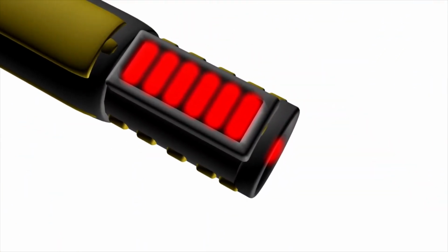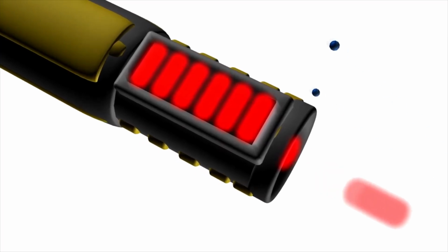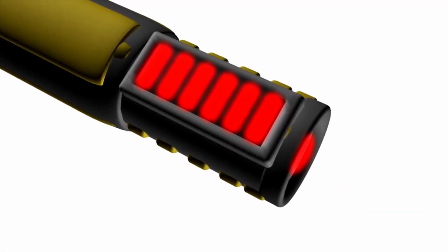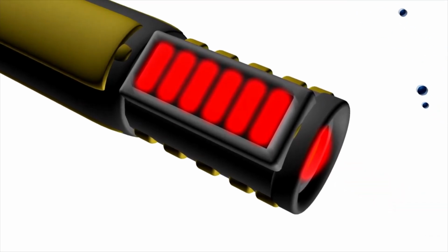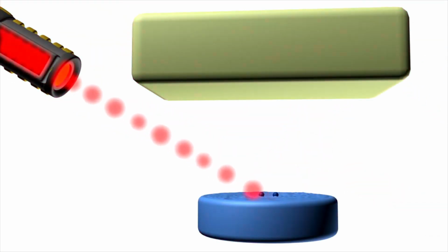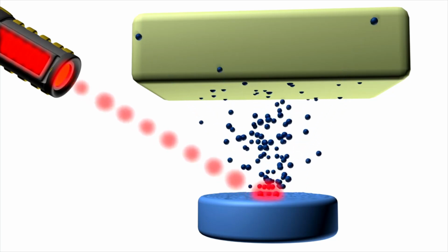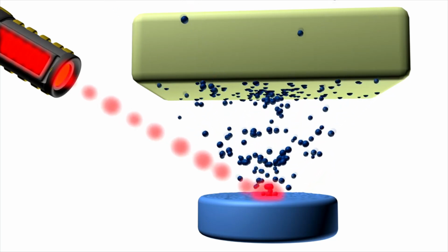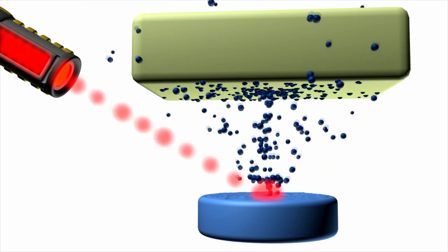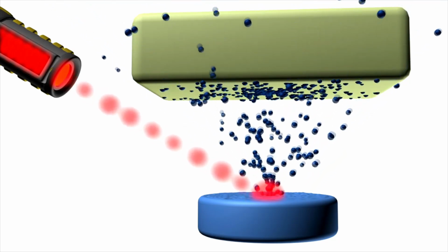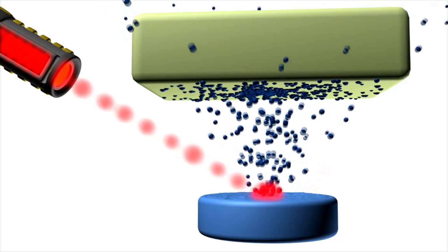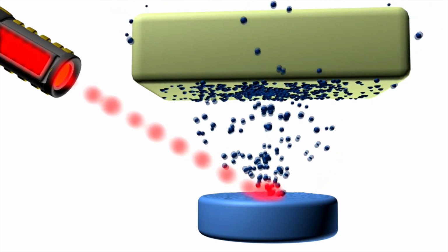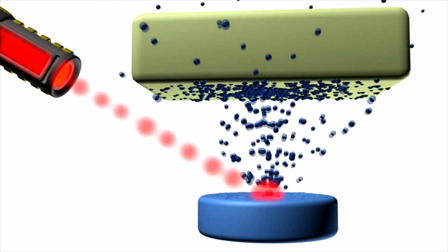The intensity, wavelength and length of the laser pulses also have a significant effect on the excitation mechanism that takes place on the target surface. For instance, using a laser with short pulses, shorter than 1 picosecond, electrostatic ablation occurs, in which case the electrons that hold the material together are excited so fast that they leave the material, resulting in an explosion of the small amount of target surface.